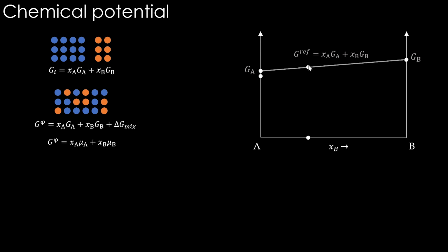From there, how the Gibbs energy of pure element A will change. The Gibbs energy of A will go down to this value, not as high as the previous case. This is the new chemical potential for A. Similarly, for B, the chemical potential will be far lower, because for this total overall composition, this is how the chemical potentials will be. So this is where it is going to lie. So this is the Gibbs energy of solution. Right. So this is the delta G mix now.